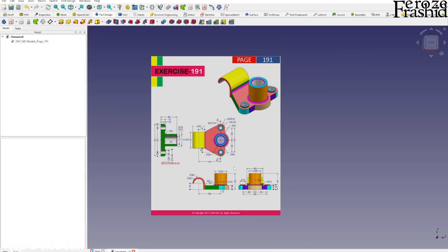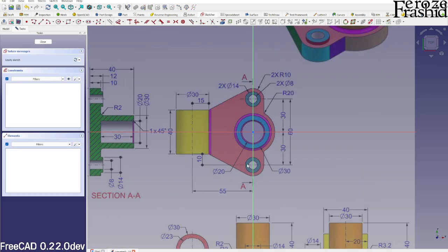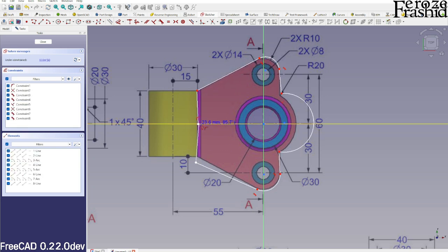As I said, I want to start off with this top view, and I will be building this base pad to begin with. Just know that this center hole does not go through, only these two edge holes will be through holes. With that, let's start sketching on the XY plane, take a polyline and draw this outside real quick. Alright, we got the polyline outline.